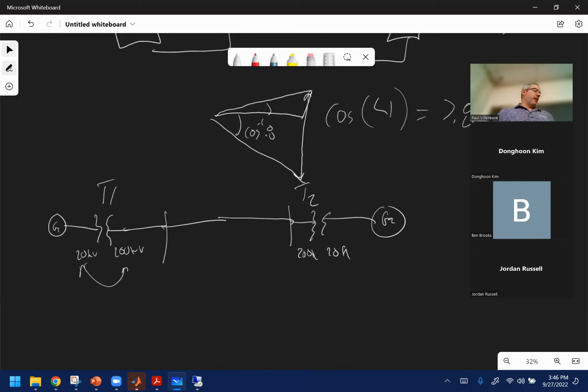You have to be able to interpret the data just like you did on the per unit one-line diagram, where we just had a rating of the transformer that we would step up or down. We would just say, here's a low voltage winding, here's a high voltage winding. You had to figure out which side was the low voltage connection and which one was the high voltage.